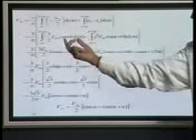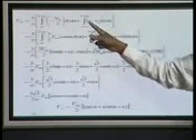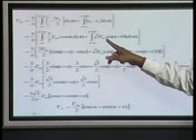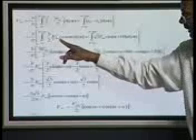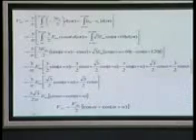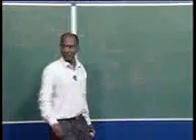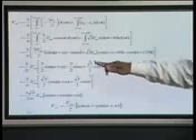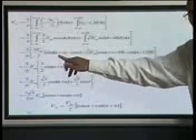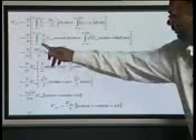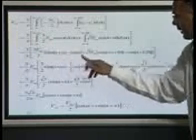So this component is appearing here, and this is the line to line voltage EBC, which is root 3 EM. This was your phase voltage, so that's why it was EM here. Simply you integrate it, put the values, and you will get this value. I am not going to integrate and put the values; you can see in the steps they are written very well. Here cosine becomes sine on integration, so this is the integration from alpha to alpha plus u. Here we got this term.